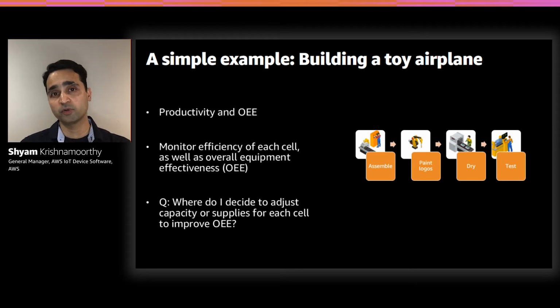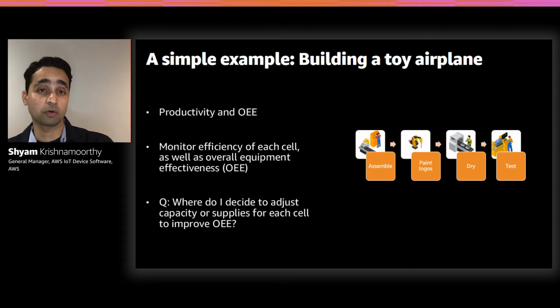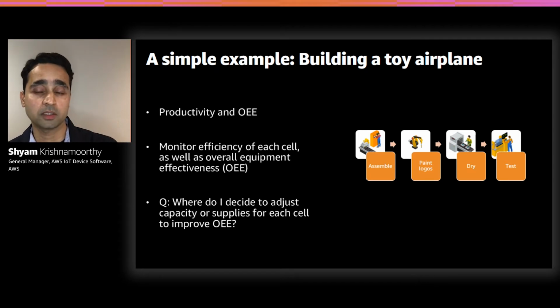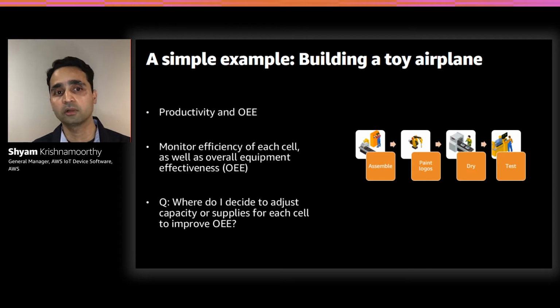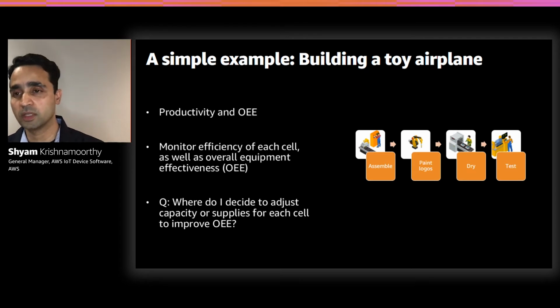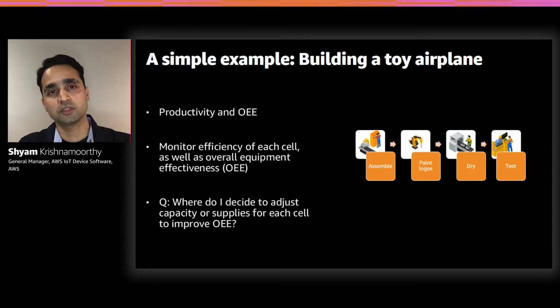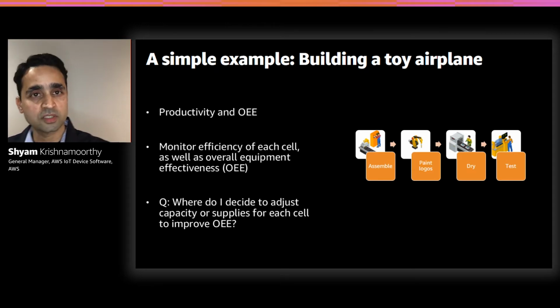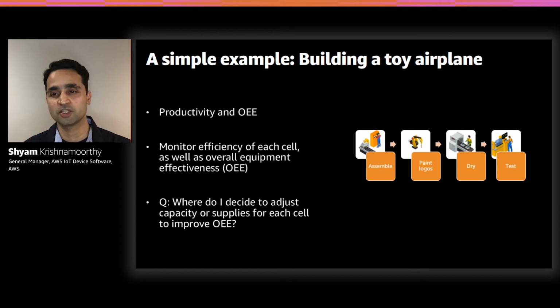Lastly, you put it all together into building the entire system, and you've got a process engineer saying, am I producing the number of units that my order needs today? Do I have the right number of people staffing the station? Do I have the right parts? And is there a bottleneck between my stations? So for overall equipment effectiveness, or OEE, that they measure, you want process engineers to be able to use industrial IoT to measure the throughput of each of these devices and make optimizations.